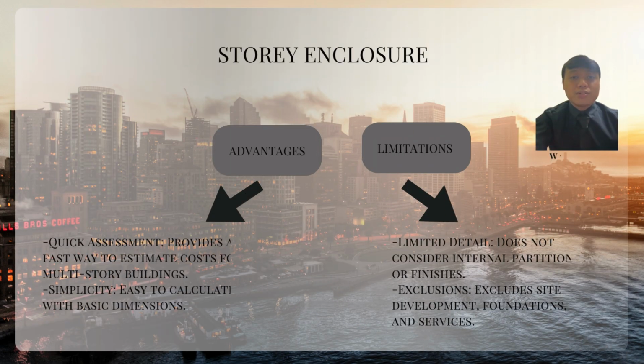Number 4 is storey enclosure. Advantages: quick assessment, provides a fast way to estimate costs for multi-storey buildings. Simplicity, easy to calculate with basic dimensions. Limitation: limited detail, does not consider internal partitions or finishes. Exclusion: excludes site development, foundation, and services.